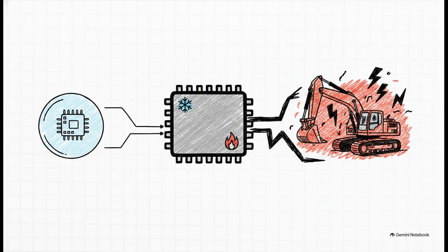To explain the working here, it translates your delicate single-ended logic signals into robust differential signals. By sending the exact same data as opposing voltages down two separate wires, that differential signaling inherently cancels out electromagnetic noise. And it does all this while surviving junction temperatures from a freezing minus 55 degrees Celsius all the way up to a blistering 150 degrees Celsius.